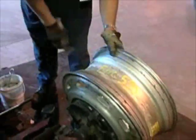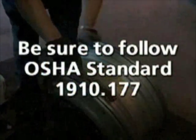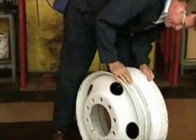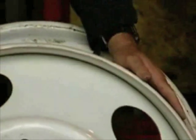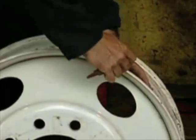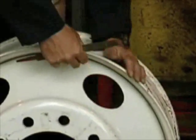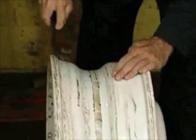Correct mounting involves attention to detail. Be sure to follow OSHA Standard 1910.177. First, you should ensure that the rim or wheel is clean and not bent, cracked, or out of round. Using a file and/or emery cloth, smooth all burrs, wells, dents, etc. that are present on the tire side of the rim. Remove rust and foreign material buildup with a wire brush.